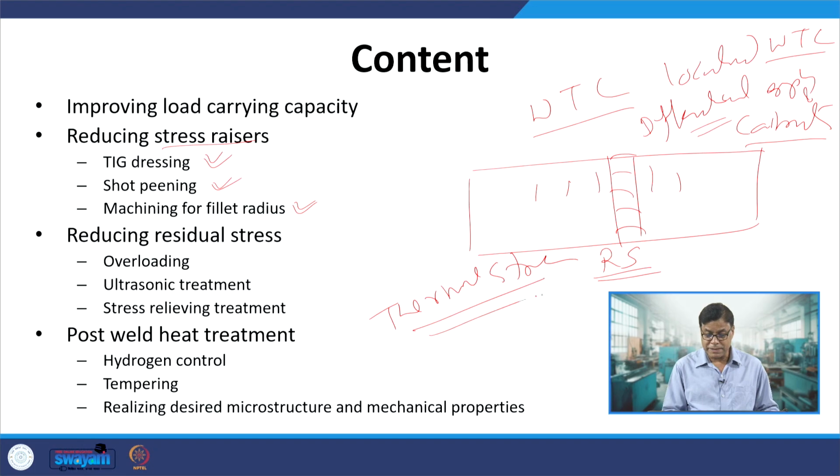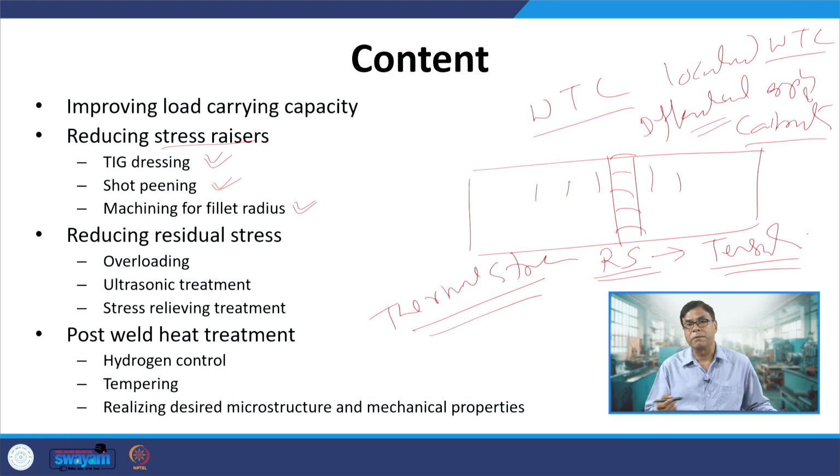Okay. The thermal stresses contribute significantly towards the residual stress development, and most of the time in fusion welding the residual stresses are tensile in nature. So, whenever we have tensile residual stresses in the weld joint, it reduces the load carrying capacity of the weld joint against tensile loading, and also the fatigue resistance under the tensile condition is minimized, and therefore